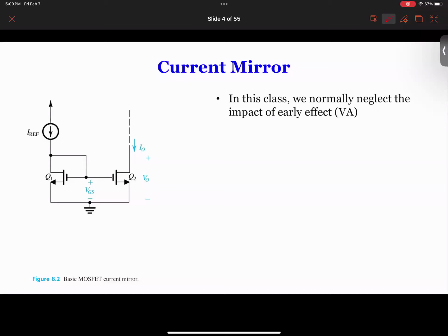In fact, instead of using a resistance here to get the current you need, we can build the reference current in different ways in the future. Think about it: we replace the resistance with a current source. So now we have a purely current mirror, no resistance at all.